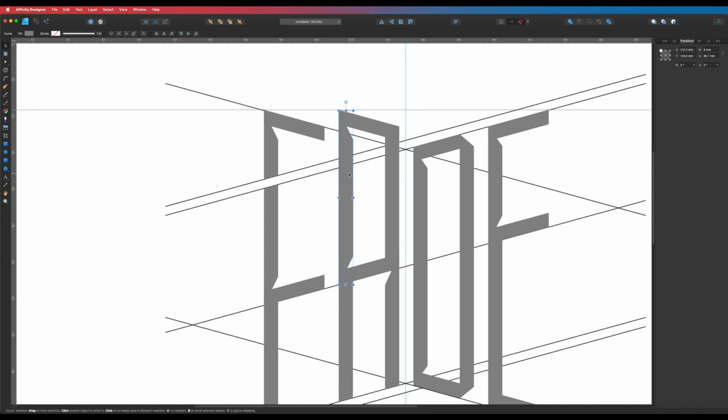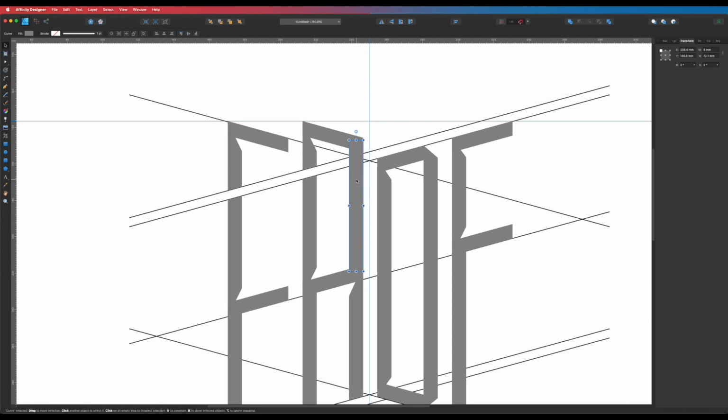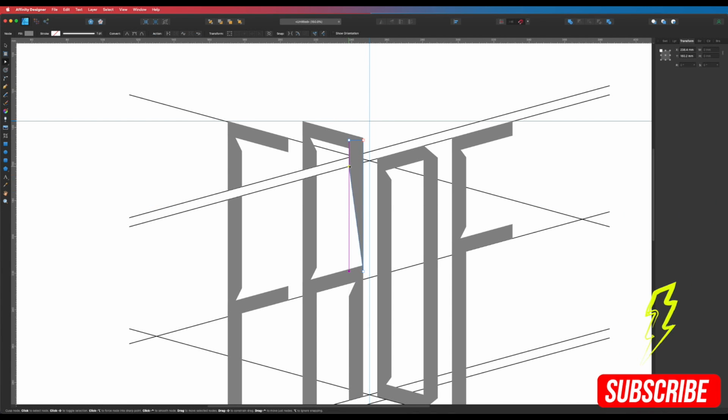I'm going to do the exact same with this A side over here. So I'm going to copy this, hit A, drag those nodes up, drag that node up, Command V, put in that shape that we already had, put it over here, and put it over here. Likewise for this side here, Command C, drag those nodes up. So you can see how everything's nicely snapping. Drag that down to here and drag that down to here. And that's looking pretty good.